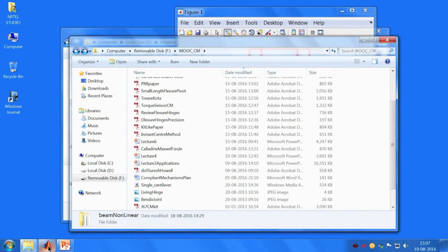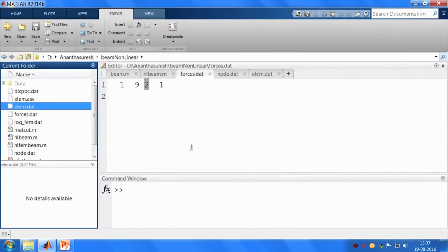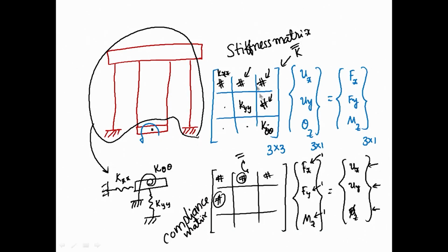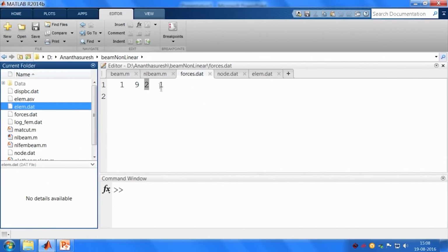Okay. You take the inverse of that, then you will get the stiffness matrix. That stiffness matrix will give you, as we saw, this stiffness matrix that let us actually go here. The stiffness matrix, first you consider C matrix by putting these things, you take inverse of that, you get this matrix, which you can actually verify with analytical formula that we did earlier in the lecture, which would give you whatever that value is you compared. Okay. And you will see the difference between linear and nonlinear FEA. So, if I do the linear and nonlinear FEA, there will be difference.